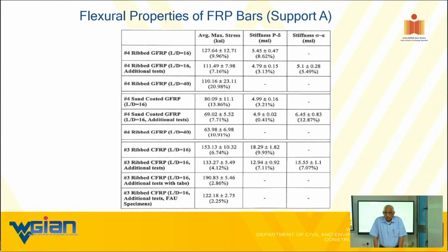Epoxies are the derivatives of vinyl ester. They're very good, except that we did not have epoxies of low viscosity till recently. That was our problem, but now we do. In the olden days epoxies had a viscosity of 2000, 1500, whatever. Today we are getting epoxy that are 150, 200 centipoise.